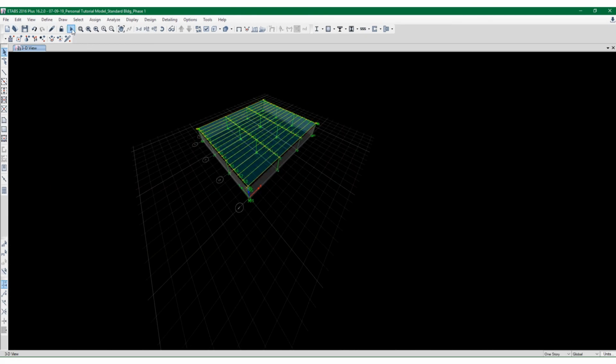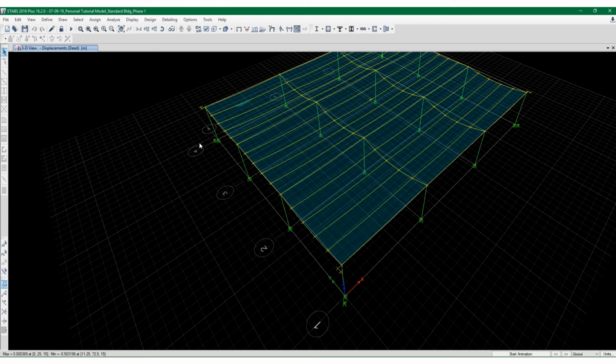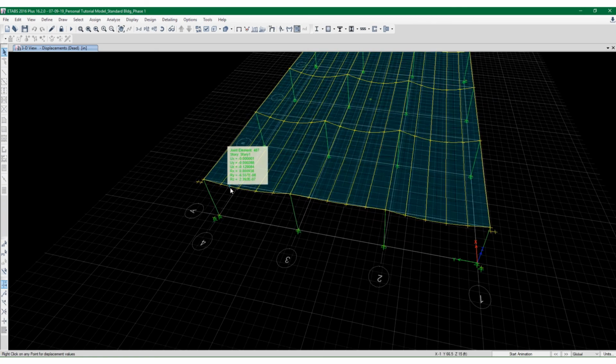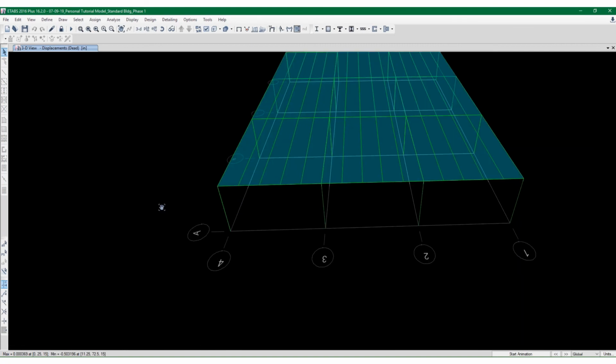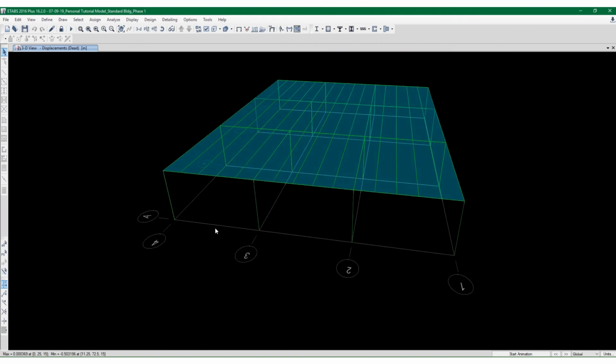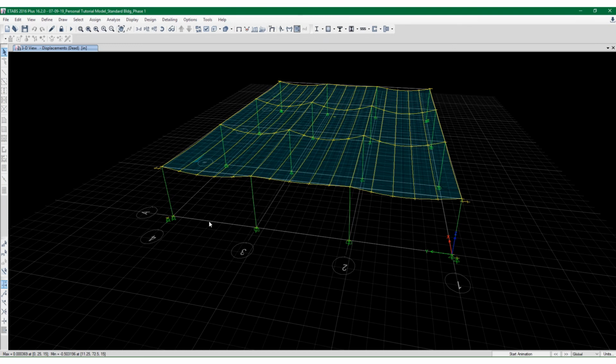Let's go ahead and run the analysis. Like I said, the only thing we did was bring this back in and tie it to the framing itself, to the center line of the framing, which is not a bad idea. In fact, if I had really big problems with my model, that's exactly what I would do. I'll put any additional loading that happens at the edges in my model directly. So I'll figure out a way to create the structural model that I need to analyze.